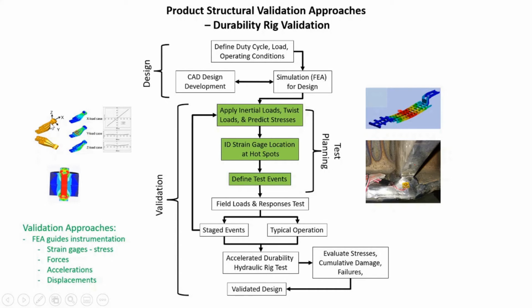In addition to strain gauge location, other things can be done to measure loads. Parts can be turned into transducers, and this depends on the nature of the part, but they can be instrumented and calibrated to directly output forces. And in addition to strain gauges, we may strain gauge bolts, because all of the connections on the structure are very important. Sometimes we may want to put gauges on a bolt to measure its tension and bending loads as part of an evaluation of that bolted joint connection.